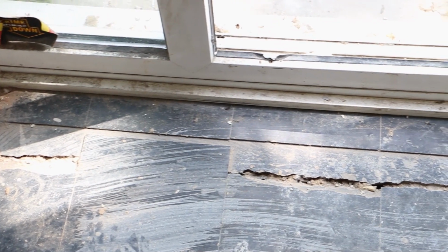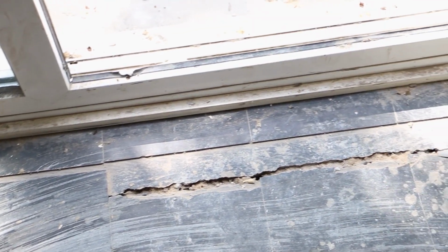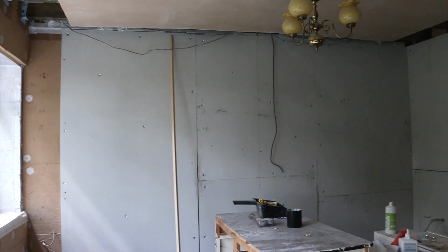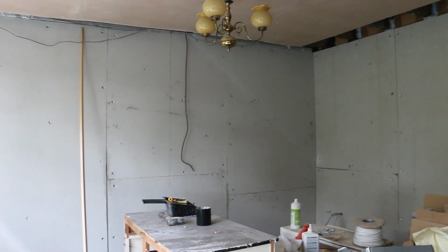If you are adding or replacing a layer on more than 50% of an external wall, roof, or floor, then the Part L targets apply. That means re-roofing, replastering, re-rendering, or reflooring are all regulated under Part L. These common building jobs are good opportunities to install appropriate insulation, and you may need to do so to meet the building regulations targets.